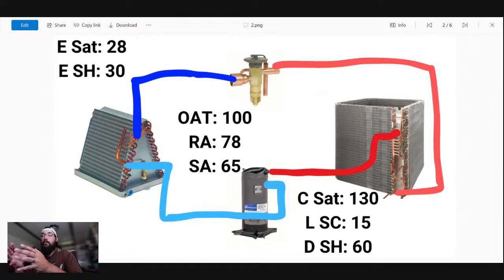So you have some options here. Now, I did somewhat specifically choose this TXV. This is not a practice that everybody uses, but I am a proponent, I think is the right word. I believe in calibrating and adjusting TXVs when it's appropriate. It should not be a first case scenario. You should really rule everything else out before you go to messing with the TXV.